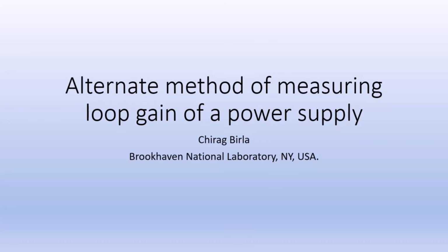Today, I will demonstrate an alternate method of measuring the loop gain of a power supply. To give some context regarding this measurement, I was testing a power supply which I had to characterize by performing step response, noise measurements, and the loop gain. Initially, I started by doing the loop gain measurements using the Middlebrook method, and then I realized that with respect to my system, there's another way that I could use to measure the loop gain. So let's look into that.